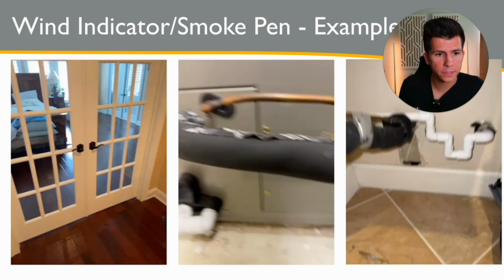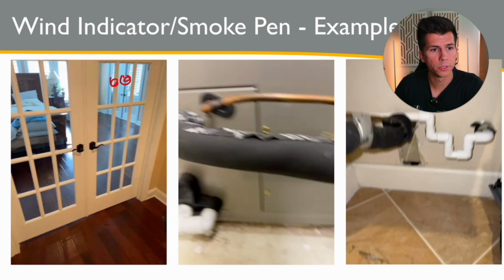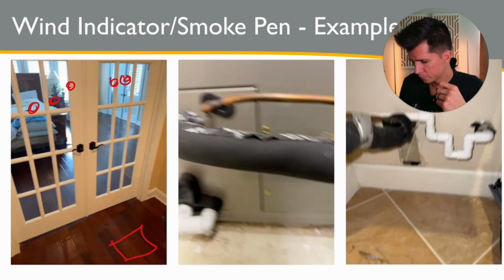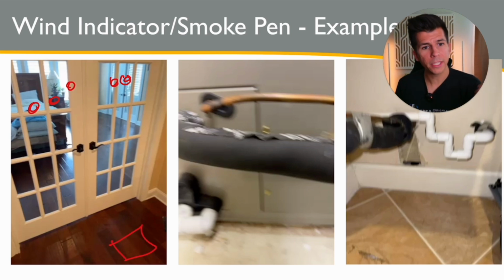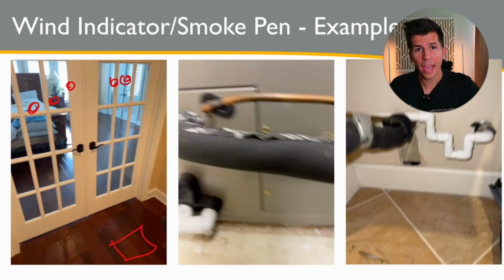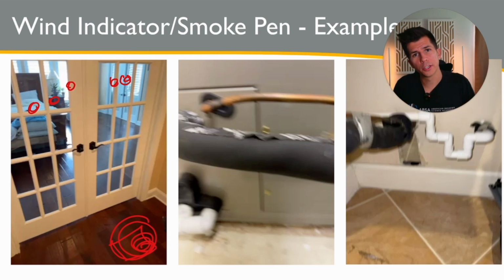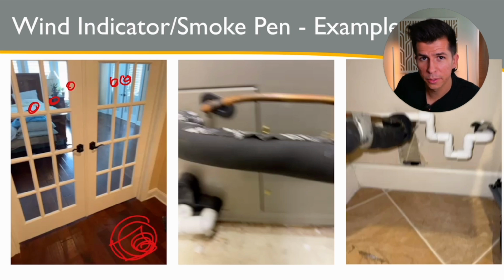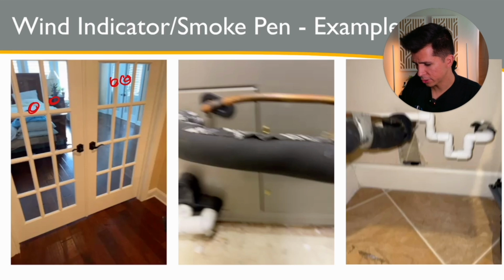All right, so we have a room where there were nothing but supply vents in this room, a lot of them. It's a big area, nothing but supply vents. And the return was in here, in this room. What does that mean? That means you're adding air into that room. You're adding and adding and adding. And then in this area of the house, the central area of the house, you're pulling. So you're pulling more air than you're getting back in the central area, and you're adding air into what was the master suite. What do you think is going to happen? Well, you're going to have pressure imbalances, right?